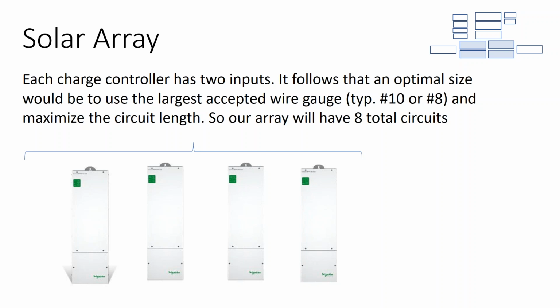So I think in all of, especially with off-grid, it's good to start by looking at the terminals and saying, okay, my battery terminals, the largest terminal size is 2 gauge, and so I'm going to start with 2 gauge. There's really no reason to go smaller than that. If we're talking about a 7-foot battery cable run, you want to have the least resistance in those cables possible.